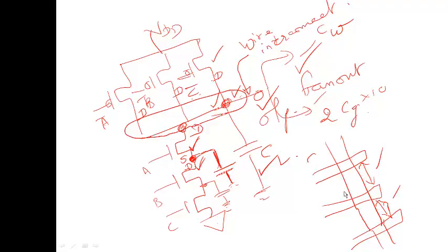Because in this structure, you have the area capacitance and the perimeter capacitance of this source terminal and the drain terminal. If they are both connected in series without any metal interconnection in between, we normally assume the capacitance is divided into two. That is, half belongs to this device and half belongs to the bottom device. That's how we assume.